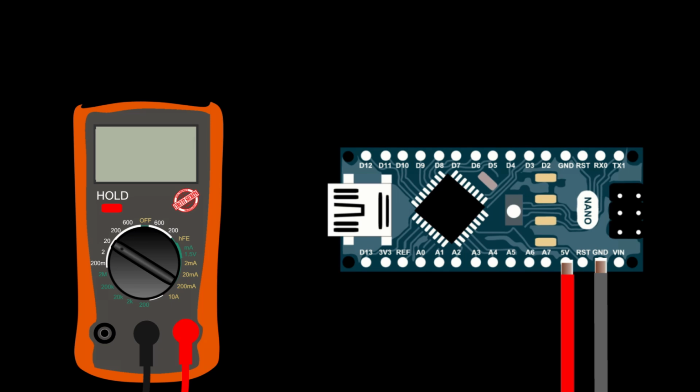If, however, the meter is set to a scale of 200 volts and a measurement is made on a 9-volt source, the meter will not be damaged, but the accuracy may be impacted, and there's a chance the meter will not measure the voltage correctly. This is particularly a factor on older meters.